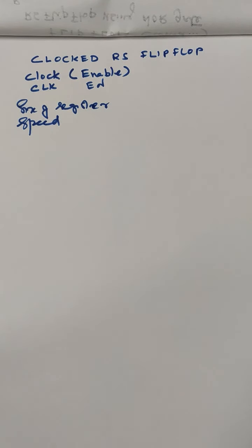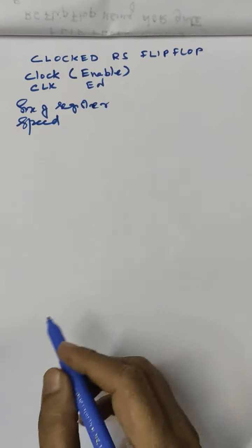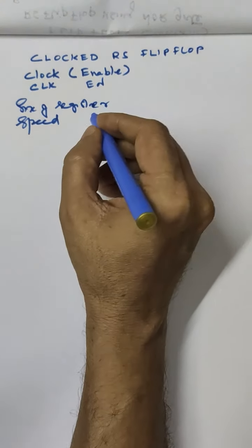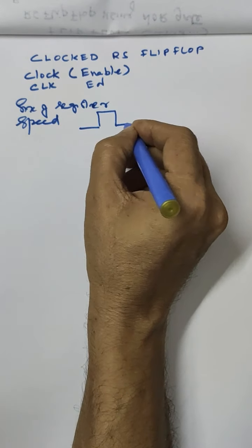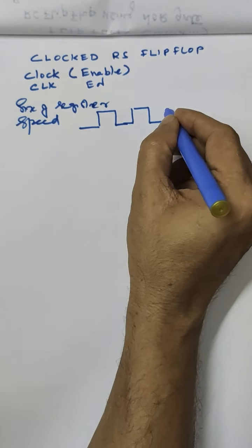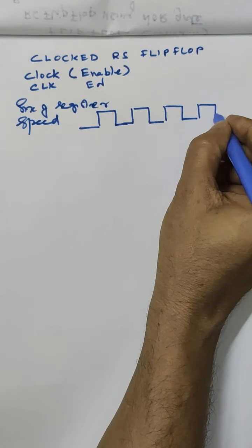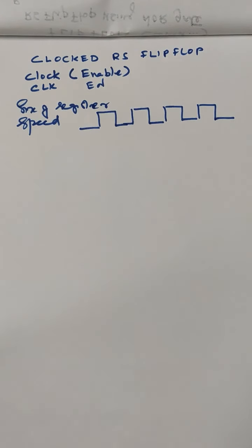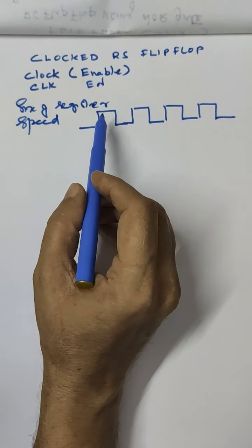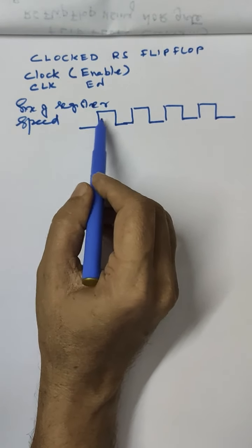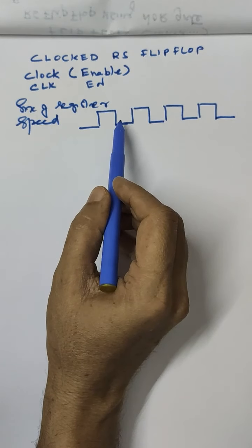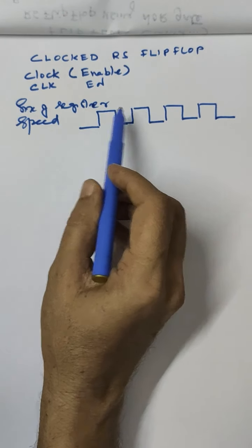So the clock is running to all components so that the operations of the different units in a computer are synchronized. This is basically an additional control over different circuits. Actually clock is a square wave. Frequency of the square wave is represented as the clock speed. The system is designed in such a way that certain operations are performed during some half cycles, certain operations during other half cycles, and so on.